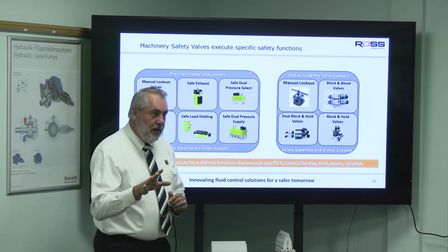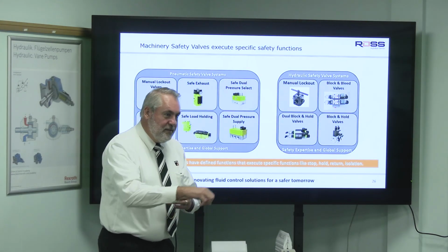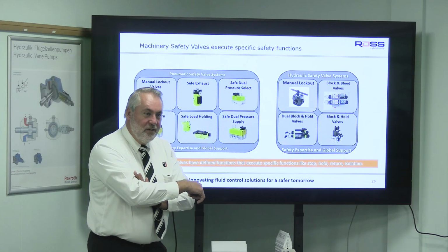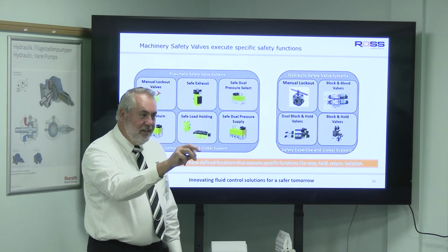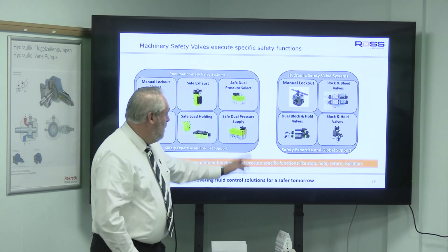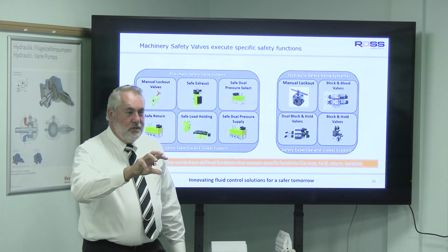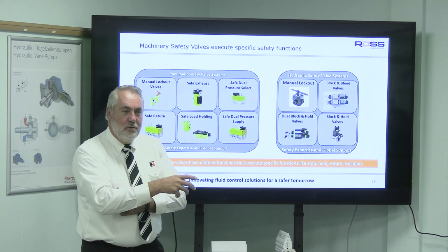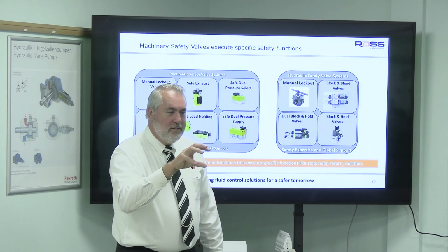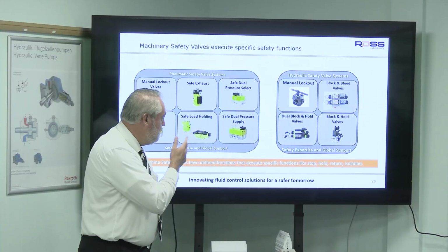Anyone ever heard the term collaborative robots? Those collaborative robots, what they do is they slow the robot down and they limit the torque so that it won't kill someone. Well, the problem is you got tooling on the end. That tooling's at full pressure. It'll still crush your hand right off. We're doing what we call pressure select, and we're switching between high and low pressure, just like they're doing with the robot. When someone goes into the area where the robot is, now it's at a lower pressure that wouldn't create an injury. Still does its job function, it's just doing it differently.